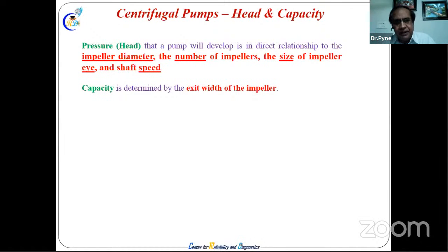But it is very bad for a plant. Today they're installing a machine, and within 2 years, 3 years, they want to go for VFD. It is not good engineering, I say, because either you have not visualized what the requirement is after 2 years, 3 years.